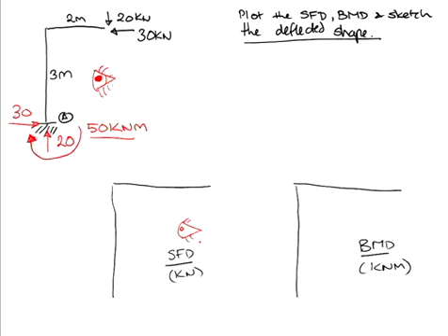Okay, shear force diagram is relatively easy. The way I've drawn the eye means I'm looking at it from the right. So you start at the left-hand end, so the bottom would be the left-hand end. I step down a value of 30. There's no load change, I step up. And what brings it back to 0 here is this horizontal load. Now when I draw the shear force diagram in the horizontal part of the structure, I step up a value of 20, I move across, and then I step down 20.